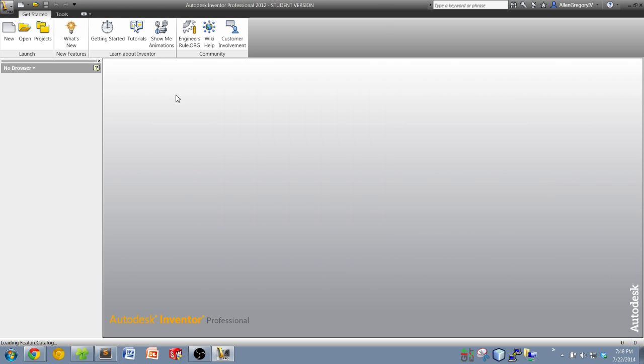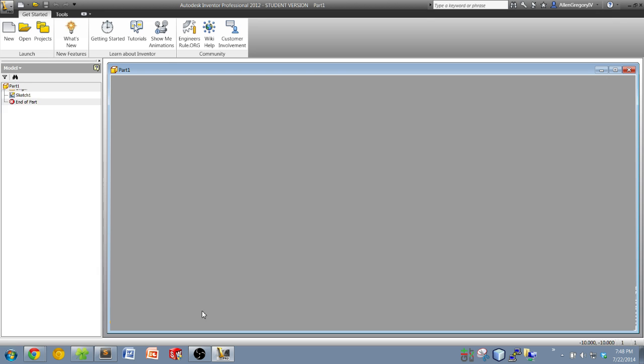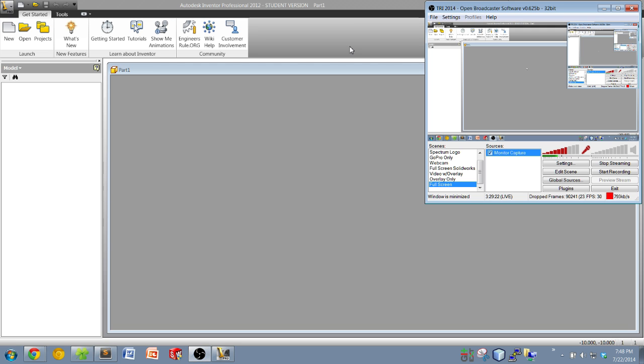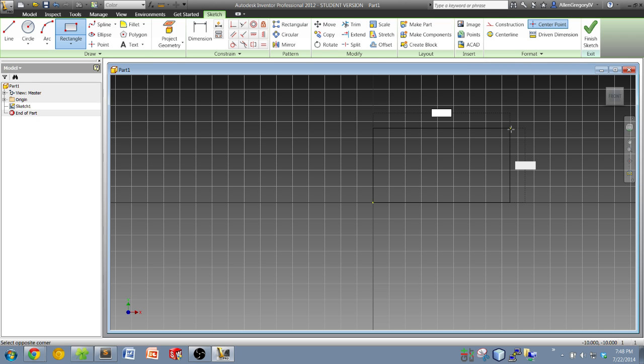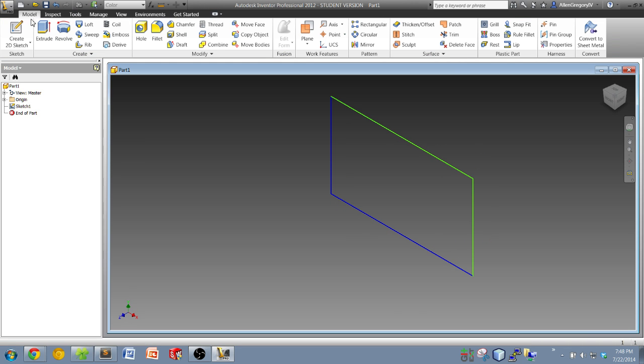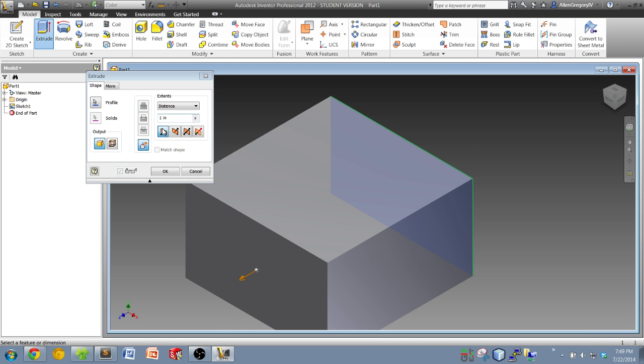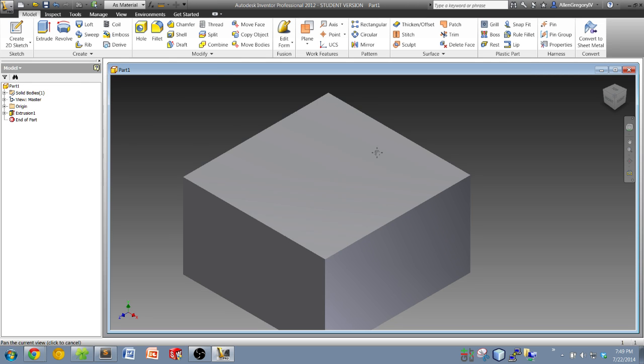So you open a standard part. We make a part file. Oops. Broke everything. Okay. So we can make a rectangle. It also does a 2-point rectangle. Then I can tell it to finish sketch, so it doesn't have the nice little tabs and everything that it does before, but they have the tabs that are just up top. Then I can extrude the same way I would before. I now have a new circle. So all of that's the same.